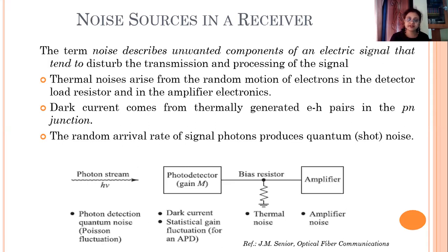Then it comes to the photodetector itself. We studied in the second lecture the photodetector operation principle, its structure, and its fabrication process. Generally in any photodetector, the fabrication process and the materials used decide its performance figures, and one of the figures which I have explained is the dark current. This is the current that flows in the photodetector in the absence of light falling on it. This is due to some carriers which are generated because of room temperature, the thermally generated electrons or carriers.